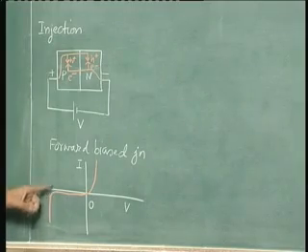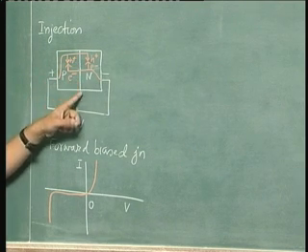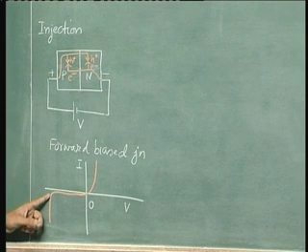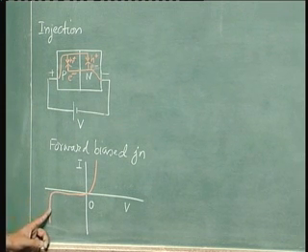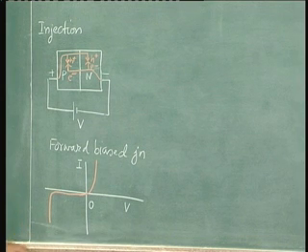So for this reverse voltage, a high electric field is created near the junction, which may give rise to excess electron hole pairs because of impact ionization, or it could also be what is called tunneling. So tunneling is another method by which excess carriers can be created. So an example of excess carrier creation by tunneling is in a tunnel diode.